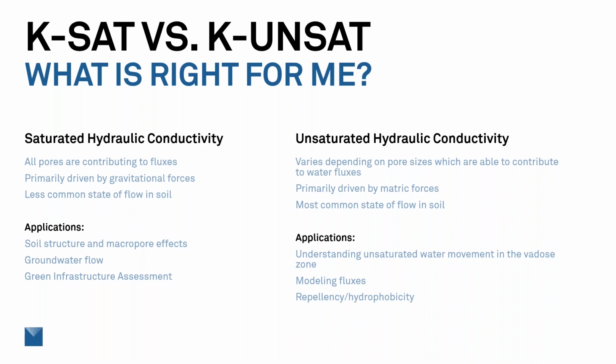So let's think about applications and where you'd want to measure saturated versus unsaturated hydraulic conductivity. As we showed before, soil structure and macropore effects are going to be more prevalent in the saturated conditions. We're going to be able to capture those. So let's say, for example, I'm trying to look at maybe a soil health impact or improvements in soil structure or those types of things. We're not going to really see something like that when we're measuring unsaturated hydraulic conductivity. So saturated hydraulic conductivity can be a lot more powerful when trying to look at these types of effects.